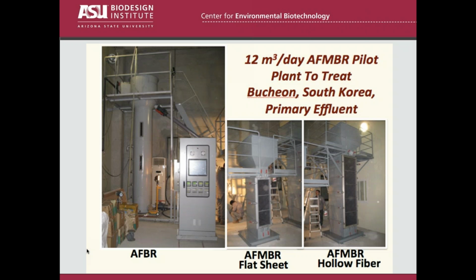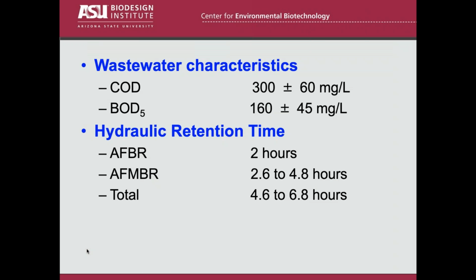So they tested this with real primary effluent, primary sedimentation effluent. So it's domestic wastewater after sedimentation. And here, of course, typical characteristics you'd expect for primary effluent, BOD and COD going in. Now, what's really important on this slide is to note the hydraulic retention times of the system. First stage, 2 hours. Second stage, well, they tried a few things, but none of them were very long, 2.6 to 4.8 hours, so that the total hydraulic retention time of the system was less than 7 hours. So this is not a big system. It's not taking up a lot of room, no big footprint on it.